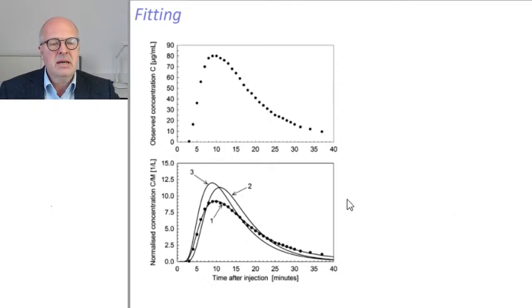And this is how it looks. So you try to actually find the parameters that reproduce your measurements exactly by changing the average velocity, by changing the dispersion coefficient, longitudinal, transversal, and that's it basically.